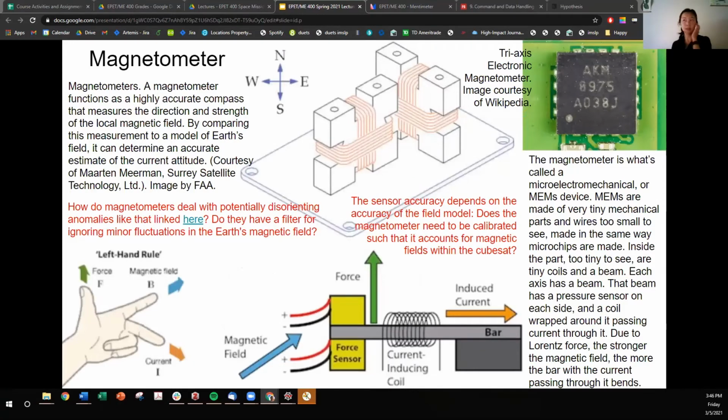Okay, now let's move on to in situ sensors. So there are magnetometers that take advantage of the existence of a magnetic field to measure what the local field is. So there's Earth's global field, but you're only sampling at a distinct point in that field. So that local magnetic field where you're sampling will be measured by the spacecraft, and given something like a magnetic field model that is loaded onto the spacecraft, you can figure out based off of that measurement where you are in space.